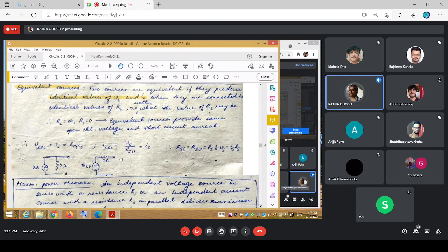Looking from this side, you can map back into your choice of a model, whether a voltage source with a series internal resistance, or equivalently a current source with a corresponding parallel internal resistance. It is your choice as the engineer to decide upon this model or that model, if it's an unknown circuit you're looking at.